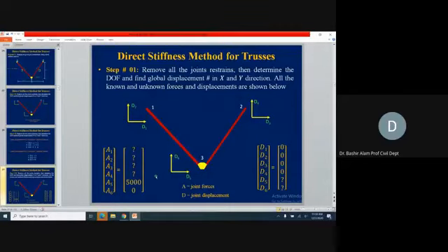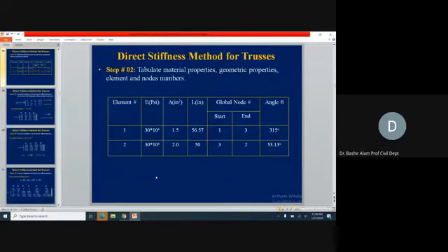This way we make our D matrix an external action matrix. And what is the relation now? The relation is A is equal to S times D. D is known, A is known. Now, the stiffness coefficient matrix we need to find out. So let's go to that one now.